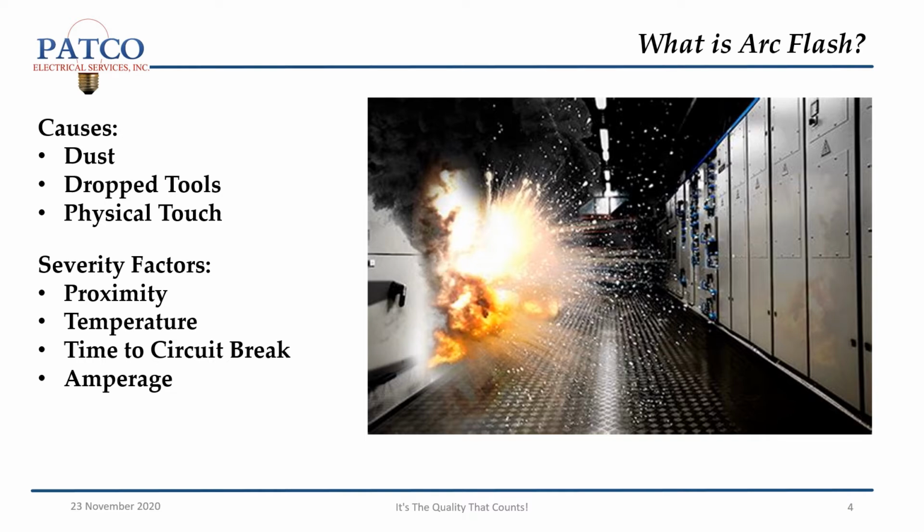Causes of arc flash can be dust, a dropped tool making contact with two different circuits, or physically touching circuits. Severity factors: proximity, how close you are to the blast, the temperature of the fire coming out, the time that the circuit breaks, and the amperage.